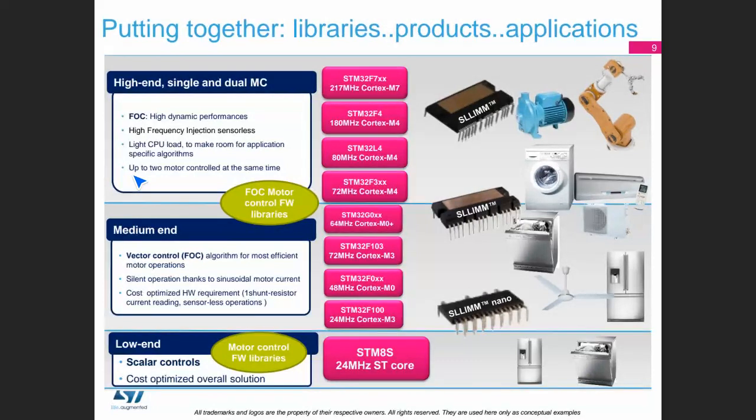I say again, a CNC machine generally uses classical position control. We have two types of motor in a position control system. One of them is the servo motor. The servo motor is high-end and high-tech because it contains a permanent magnet system, high efficiency and high dynamic control capabilities. However, if your CNC machine uses a step motor, it is very basic, very cheap, and a very old application. Step motors do not have high dynamic performance.